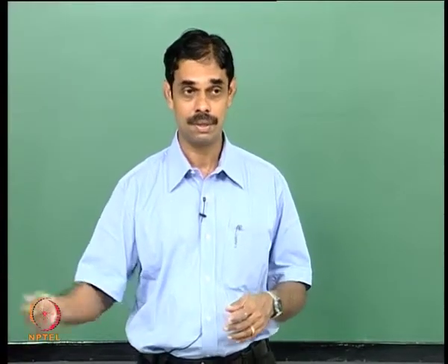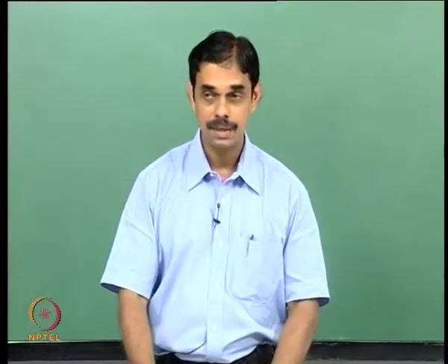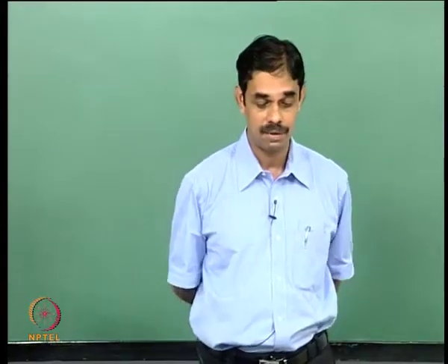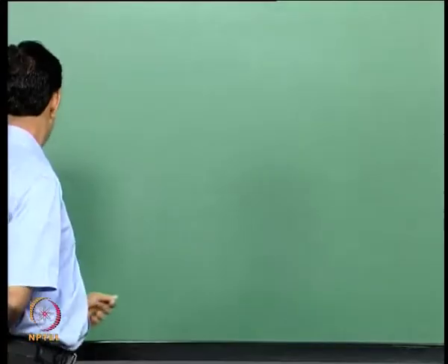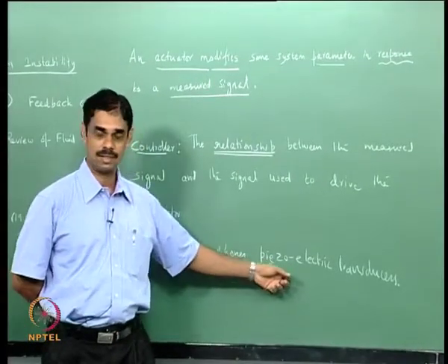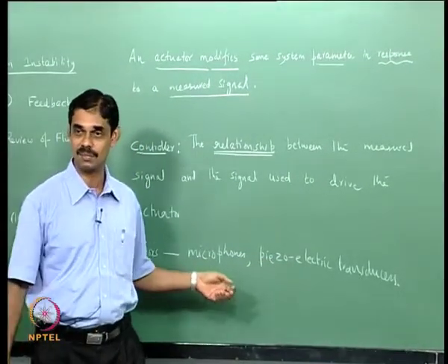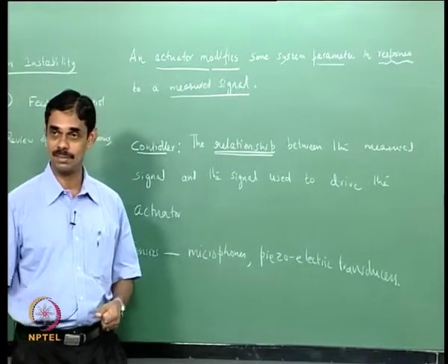So there is an option to keep them away and you can still measure it. Typically microphones have large bandwidth and they are reasonably robust. Microphones may break at large amplitude, and if you drop one it will surely get spoiled. Piezoelectric transducers are much more robust.